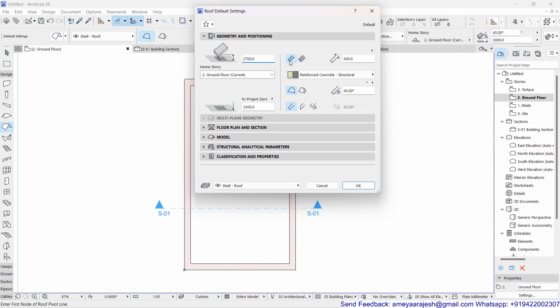After that, on the right side, you can check out there's a structure which is basic and composite. We'll continue with the basic option. Once you choose the basic, then you have to define the thickness of the roof. Remember, if you are in the composite, it will have a predefined thickness. So I'm working with the basic. Now the roof thickness can be determined with two logics, perpendicular or vertical to the floor. Okay, so this is the vertical and this is the perpendicular to slope.